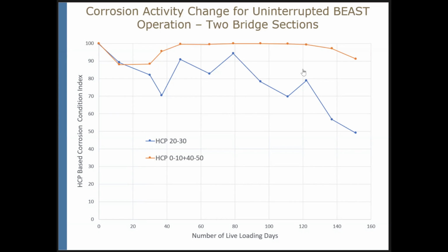Ultimately, what we obtained from all of the technology, what we learned from, for example, half-cell potential and electrical resistivities, that corrosion was definitely not a driver. We calculated what was approximately mass loss due to corrosion, and that was very minor. So it was not the driver. So what was the driver was fatigue due to repeated high-intensity live loading. And this was especially pronounced in those zones of thin concrete cover.